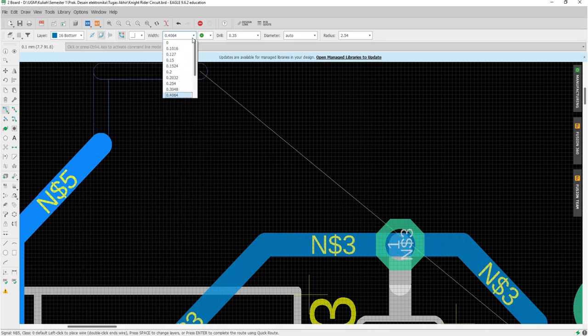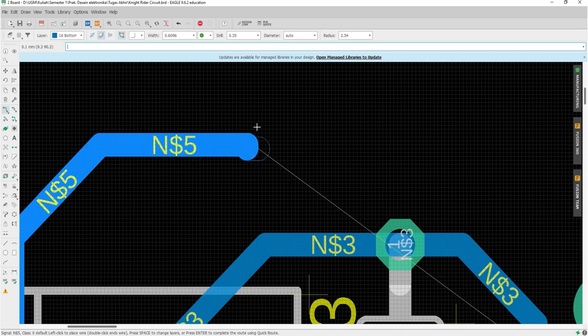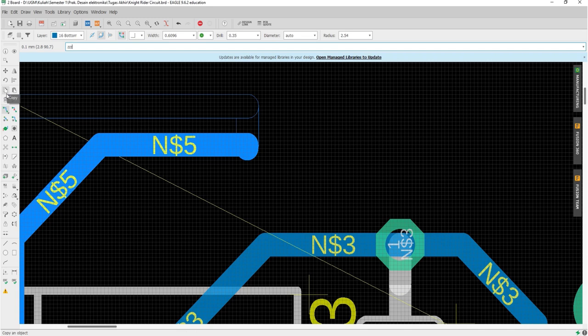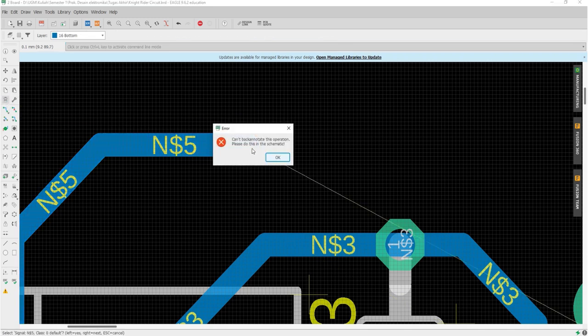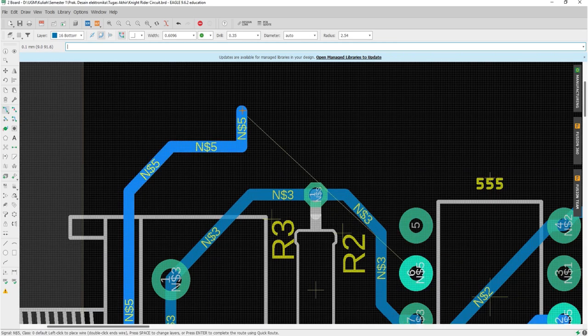When you have a bunch of traces that have a sharp right angle turn on your board, the outside corner of that 90-degree angle has the likelihood of being etched narrower than your standard trace width. And at its worst, you might get a bunch of 90-degree traces back that aren't fully etched, resulting in shorts.